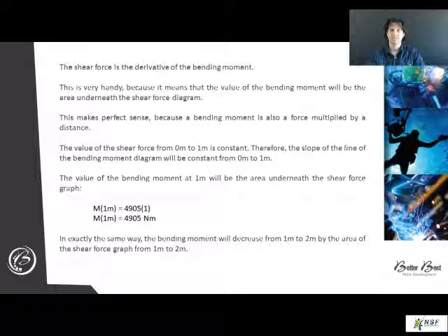The bending moment diagram can be calculated directly from the shear force diagram. The shear force is the derivative of the bending moment, or the bending moment is the integral of the shear force. This is very handy because it means that the value of the bending moment will be the area underneath the shear force diagram. This makes perfect sense because a bending moment is a force multiplied by a distance.